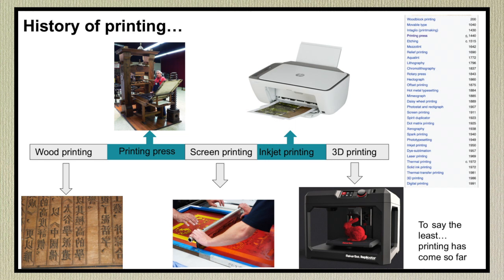This constructs a three-dimensional object. The term 3D printing refers to a variety of processes in which material is deposited and solidified under computer control to create a three-dimensional object, with materials being added such as plastics, liquids, or grains of powder being fused together layer by layer.